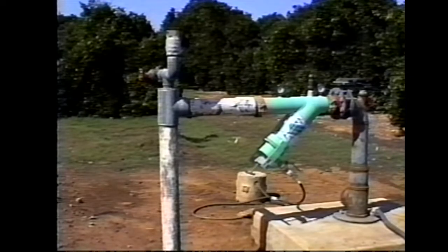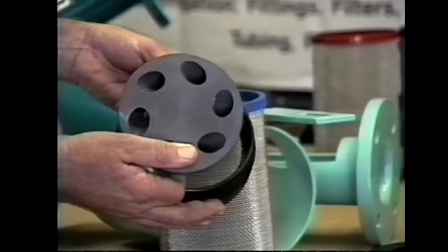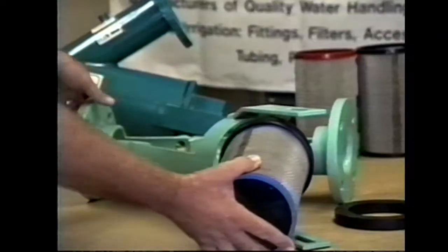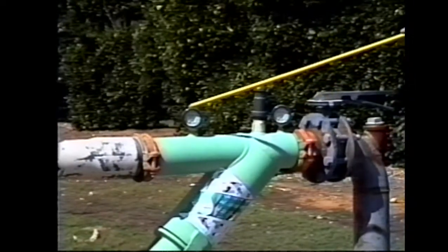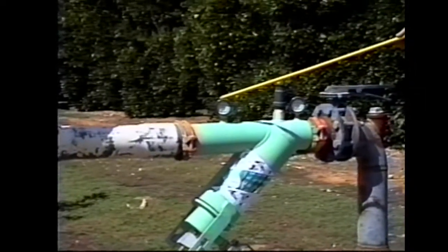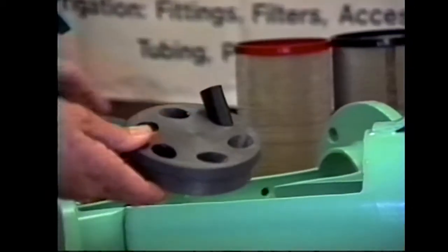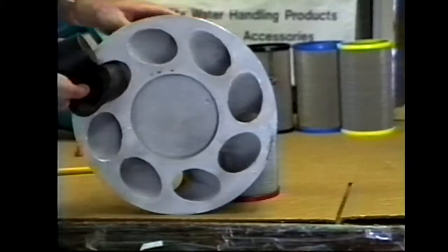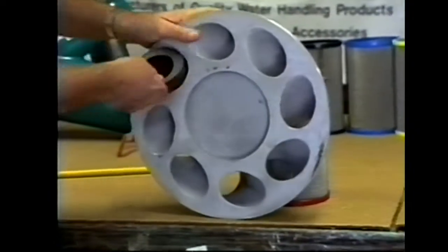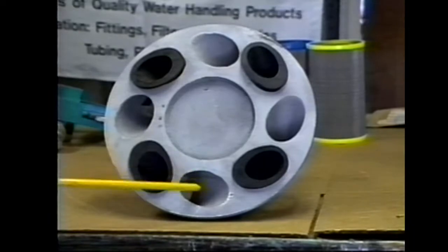Other filters combine a screen with the action of a sand separator. Such filters may use a directional nozzle plate which directs incoming water onto the inside of the screen. A head loss occurs across the spin plate when the water changes direction and accelerates the solid particles to the outside edge of the tank. Holes in the spin plate are manually plugged if the system flow is less than optimum. A pressure drop of at least 5 psi is needed across the filter. Enough holes are plugged to obtain the required pressure drop.